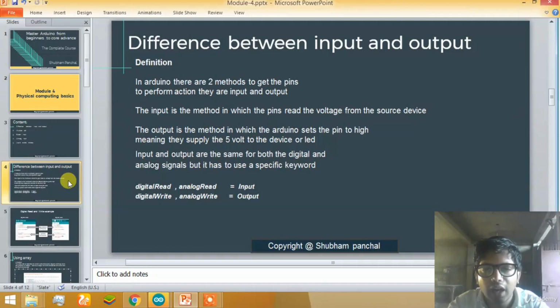Most of the pins are capable of giving an analog output or input, while every pin in the Arduino board that has a number is capable of giving an input and output in the form of digital, such as the analog pins A0 to A5 will be turned into digital pins by using the numbers digital pin 14 to digital pin 19.